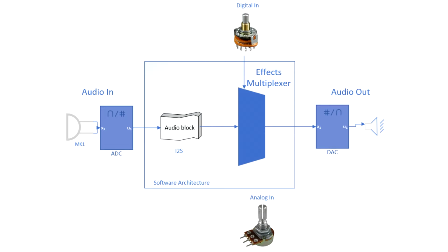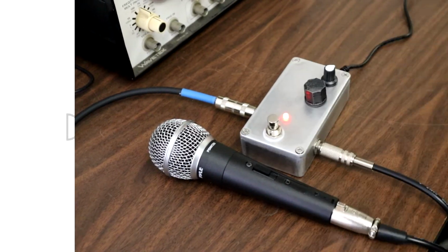The main mixer feeds into a multiplexer function, which will enable a selected effect based on the position value read by the Teensy from the rotary switch. Depending on the effect, the potentiometer will pass an alpha variable used to change their individual properties. The DIGIMUSER operates as a low latency, real-time audio system. A benefit of using the Teensy is the ability to modify pre-existing effects or program new effects into it for added versatility for the user.